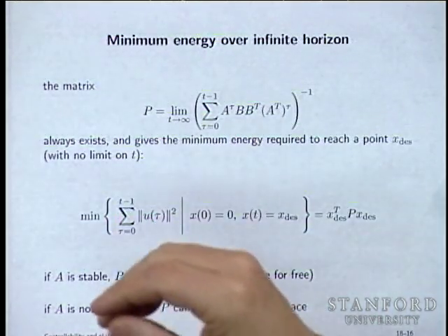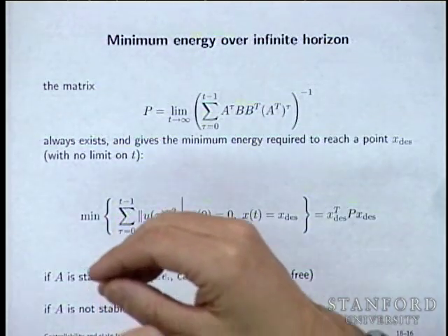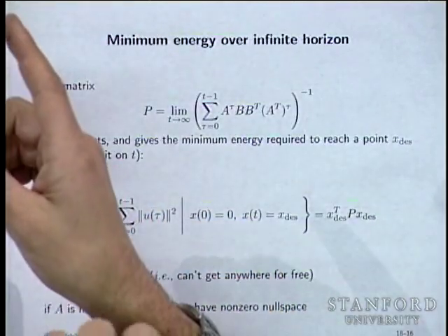You actually find out what input is required to hit that, and you take that point divided by 1.01 to the t, and that's the u you set on the first input. Now that's a sequence of inputs that just kick it out and then let the dynamics take it there. Those inputs will have, as t gets longer and longer, the energy go to 0.